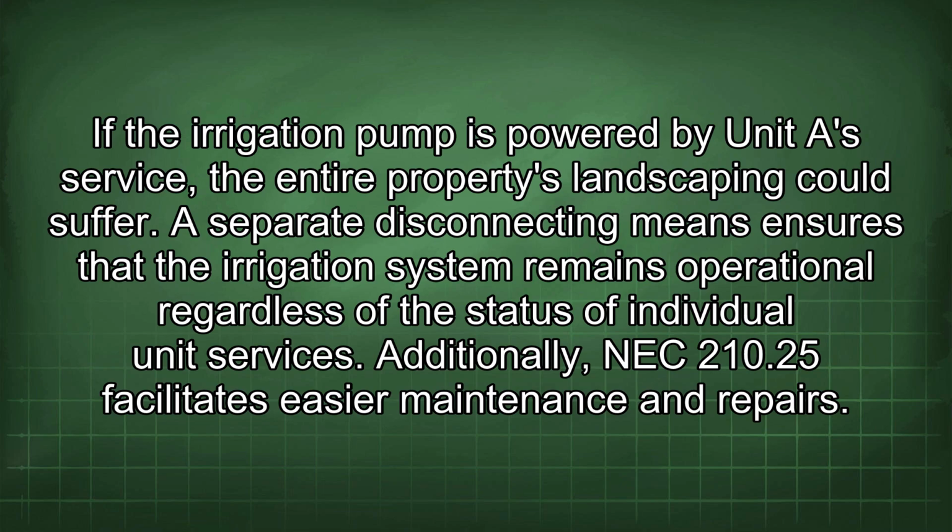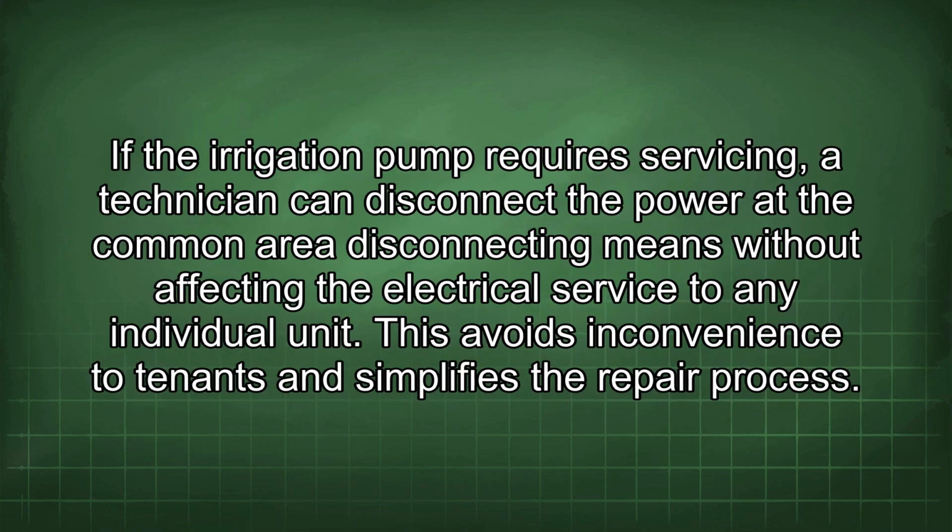Additionally, NEC 210.25 facilitates easier maintenance and repairs. If the irrigation pump requires servicing, a technician can disconnect the power at the common area disconnecting means without affecting the electrical service to any individual unit. This avoids inconvenience to tenants and simplifies the repair process.